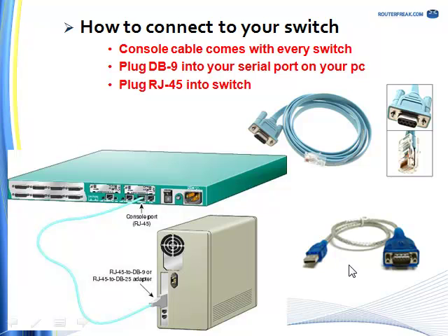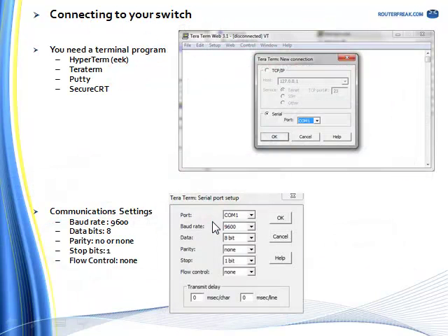One of the issues I have seen with some of these USB to DB serial adapters is that they all come with software drivers you actually have to load. Windows especially doesn't natively recognize what these devices are, so you'll have to. They all come with the disk. You load the disk on your laptop, and then it'll get loaded and it'll be fine. But in the meantime, you can't just find one of these cables laying around and plug it in and hope it'll work. You still need the driver, so just be wary of that.